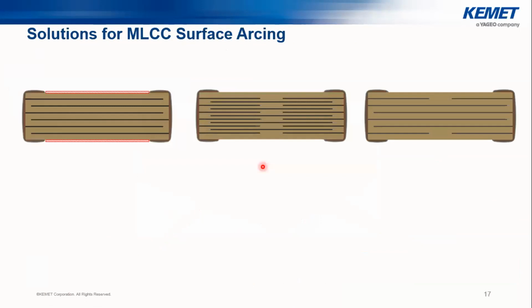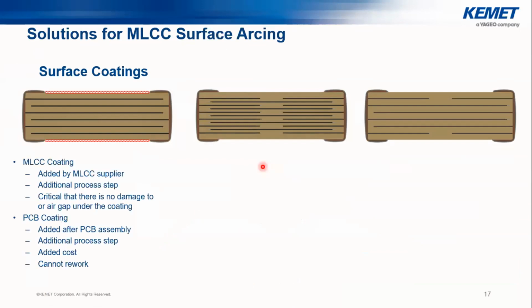But what do we have as a solution for MLCC surface arcing? We have surface coating. This can be done by the suppliers through an additional process step. It gets critical if there is any damage to the surface coating. Because of that, we also have other solutions, but it can also be done through PCB coating, which can be added to the PCB assembly as an additional process step, or also added cost.